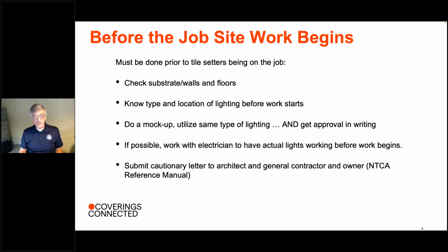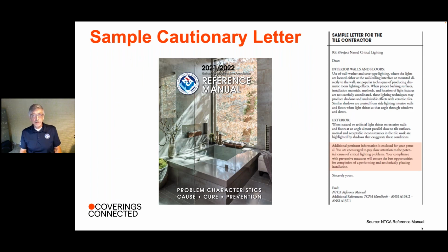Finally, after you've done this before the work begins, after you've analyzed it, submit a cautionary letter to the architect, GC, and the owner, and I'm going to show you a picture of this on the next slide. Submit a letter as the tile contractor and communicate your concerns before the work begins. Here's the NTCA reference manual. On the right-hand side of your screen, there's the sample letter for the tile contractor to use to talk about the critical lighting issues that they found that could impact their finished installation.